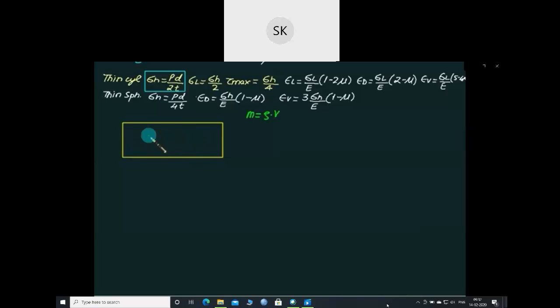But if the vessel is subjected to pressure, and you want to check that pressure, then you must create the pressure inside this one. That pressure can be created by pumping more liquid inside. So if you add delta M water inside, which is in excess of its capacity, will every water that enters pressurize this tank? If you have this capacity only, that is this volume multiplied by rho, and this amount of water you add inside, you can just check the leakage. But if you want to check the pressure, then you must add extra water inside this one.